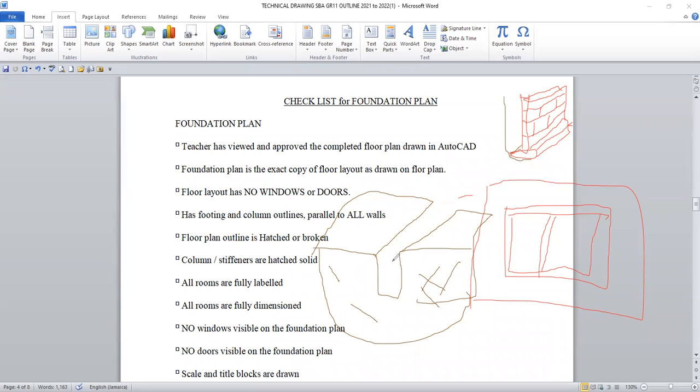We excavate or dig away this section, and we lay the footing first, which is where the building would sit. What this does is prevent the building from sinking. So we lay the footing down there first, with our reinforced bar and our concrete.